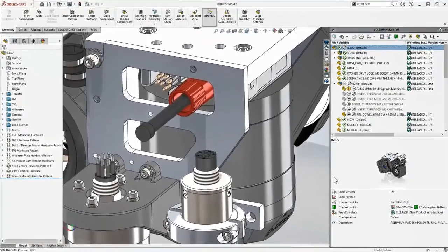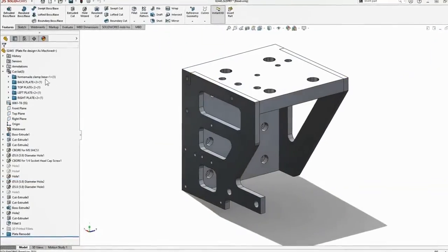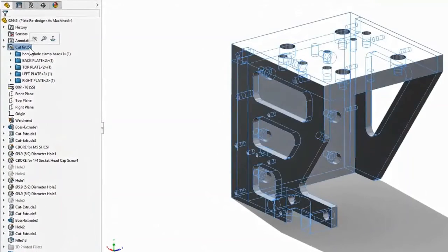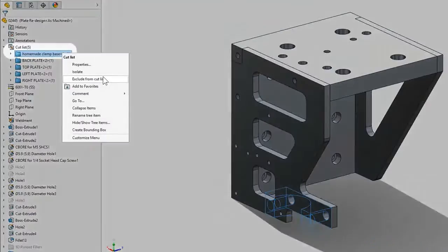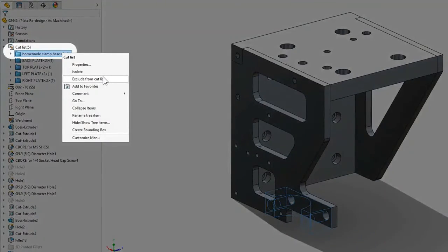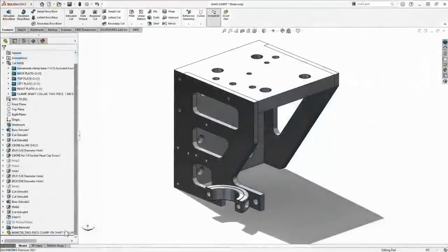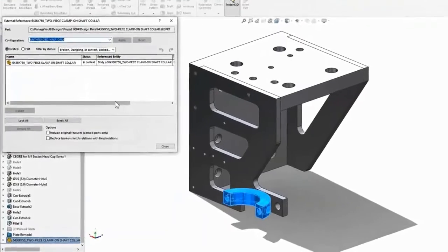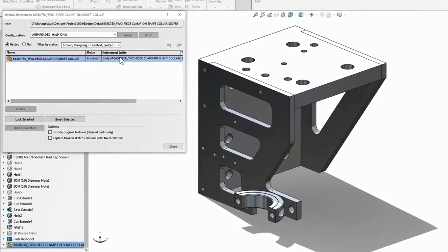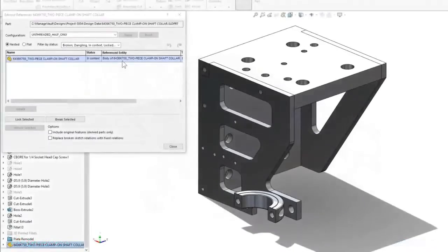In SolidWorks, new feature this year, there's added integration between the SolidWorks way of managing BOMs and PDM. Now, when you exclude something from the cut list, PDM will understand and apply the same exclusion to its own BOMs. This applies as well to reference parts like mirror.